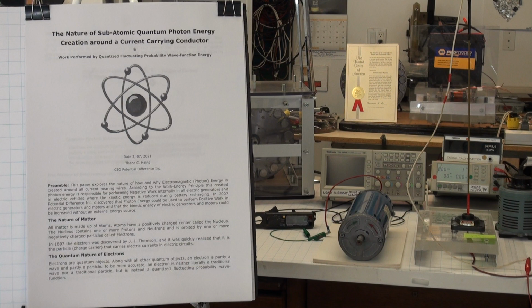Generator armature reaction is a counter electromagnetic torque which is produced inside an electric generator when the generator is placed on load and when current flows in the windings of the generator coil or coils.